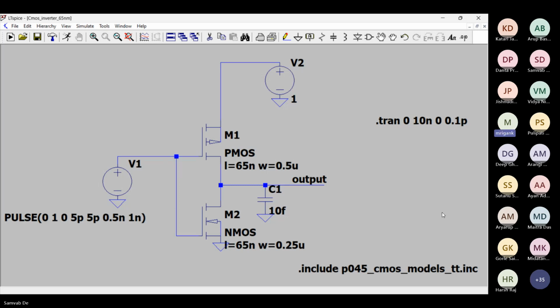And that CV charge went from VDD to ground. Therefore, total energy lost is CV times V, charge times the voltage across which the charge is transferred. So CV square energy is lost. But at what rate is it lost? CV square divided by the time period of the waveform, that means CV square times F. So CV square F is the power dissipation.